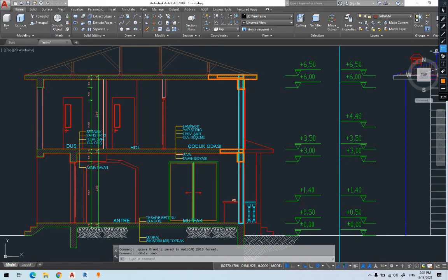So in order to do so, we need some of the elevations. So I started adding, for example, 0, which is the ground level. You might need it in case. If you don't want this one, it depends on you. Let's say 0.5, which is the bottom of the slab, in case it is required. Then I might need this one, which is the top of the first floor, and the top of the second floor.